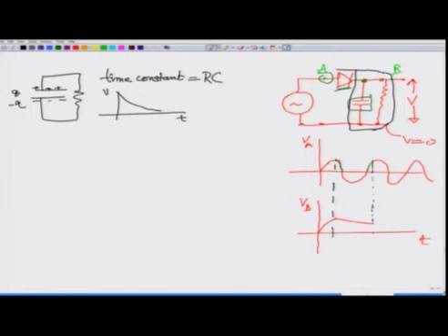I am talking of this part. In this part what is happening? In this part the capacitor voltage was decreasing, but then the voltage at point A, on the P side of this PN junction, has increased, and therefore it becomes forward biased, and therefore once again the same story, forward bias. So, the current will flow and the capacitor will get charged, it will get charged up to the maximum, up to here, let us say,